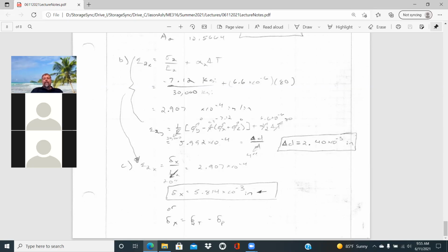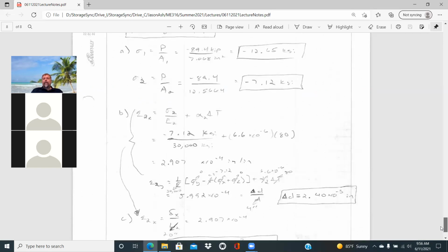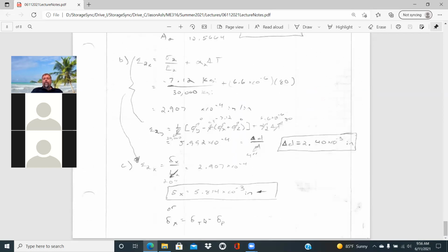And so I think this would probably be more commonly how I used to solve those things. I just kind of wanted to show you that from the Hooke's law standpoint as well. But I'd recommend you do the math on that, where the thermal displacement is alpha delta T times L, and displacement due to the load is PL over EA. And with that, you're just putting the magnitude of P in there, since I've set up the signs already for that purpose.